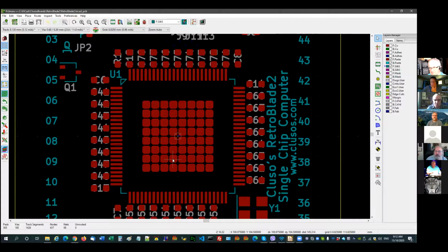It's very important to get the right size, and it looked like they'd done the job correctly. They talk about 80+% coverage, but you don't put a big blob on. And then all those wires are sitting in the little corners there, so that they don't take your solder paste away. So you still have a big pad.